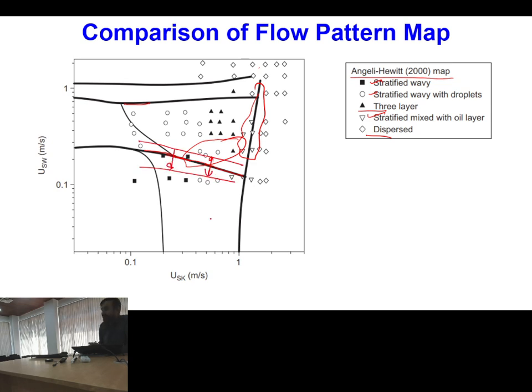wide zones. Why? Because whenever you are having one particular flow pattern, and in that flow pattern you have the presence of a perturbation, then depending upon the stability conditions, your perturbations can either amplify or die down. If the perturbation is amplifying, then the flow regime will shift from one to another.